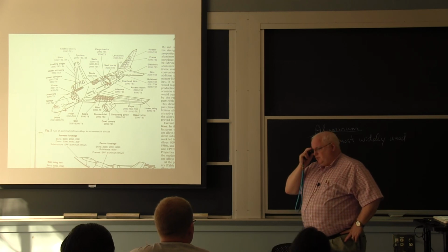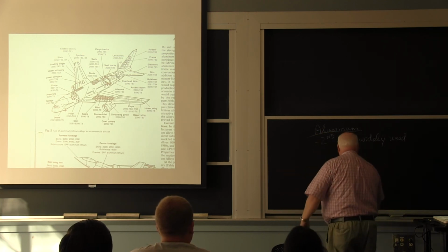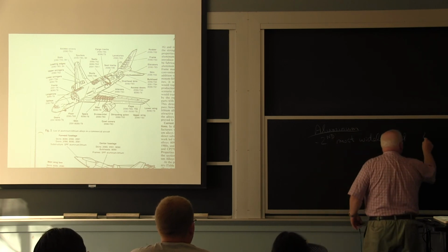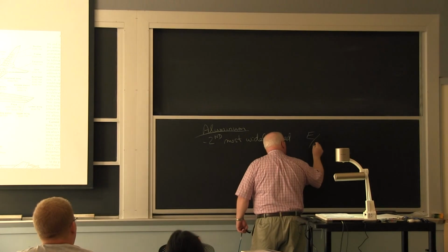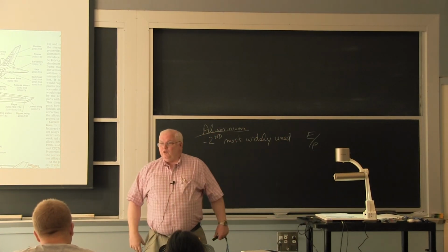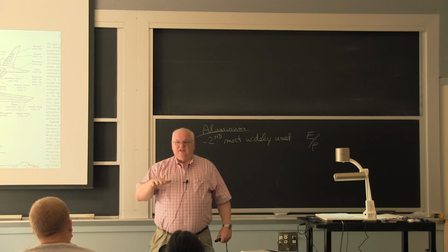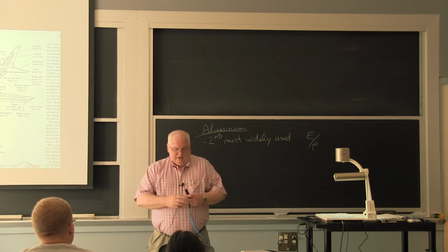Usually alloying at that level doesn't change the modulus of the material, but it actually increases the modulus by 10 or 15%. And if you look at structural beams in bending, the modulus divided by the density, E over rho, is the relevant parameter. If you get 10 or 15% higher modulus and 10% lower density, you all of a sudden get a 20-25% improvement in stiffness of your alloy. You can eliminate 25% of your weight.